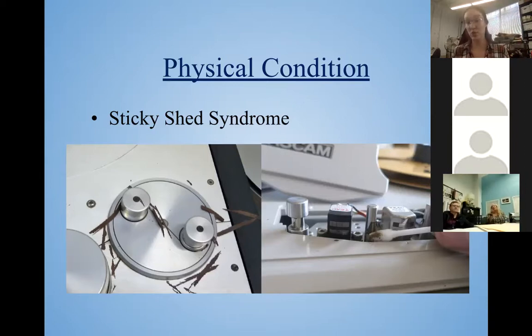But typically, the image on the right, I have found where you play the tape, you hear some squealing and you see that the tape or the playback deck is working harder than normal to play that tape. Normally if I see that and hear that little squeal, I'll stop. Another key tip that you have sticky shed syndrome, because there's no way of knowing until you start playing it, is that you play the tape and then you go to clean the heads and the moving parts that the tape touches, and you have a bunch of magnetic particles on your little Q-tip, which shouldn't happen after playing for a few seconds. That's not dirt, that's magnetic particles.